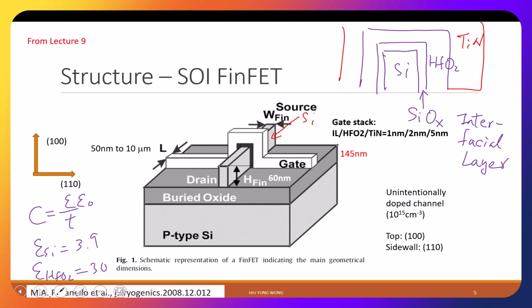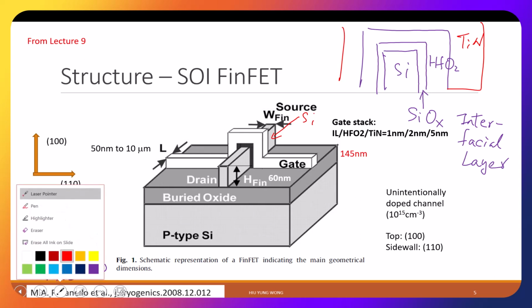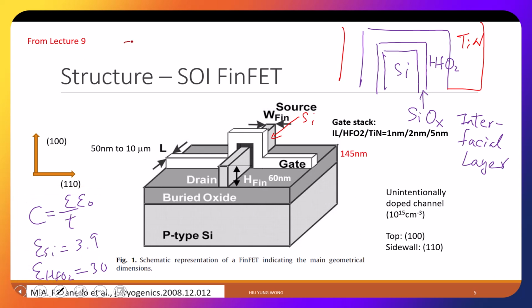The valence band of the silicon, maybe you forgot or you didn't know, but anyway, I can say a little bit more. If this is the valence band, this is the conduction band, and then you go all the way to the vacuum, right? To the vacuum. And what is the energy for electron to go to vacuum? This is about 5.1 eV. And from conduction to vacuum is about 4.05 eV, approximately. I forgot the exact number, right?